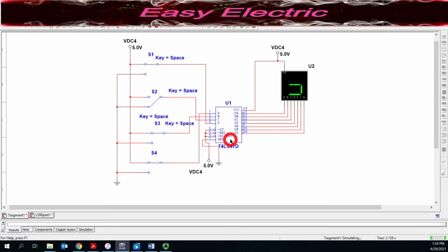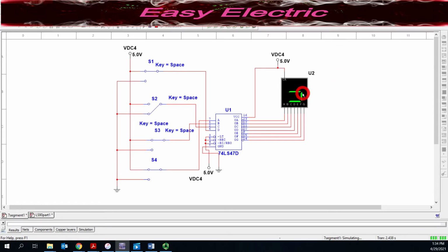And because this is BCD to 7 segment codes, we don't have 11 in our BCD, so it shouldn't show any meaningful LEDs here. The numbers that we could give are 0 to 9, because the BCD is just between 0 and 9, and see the corresponding number here on the 7 segment.